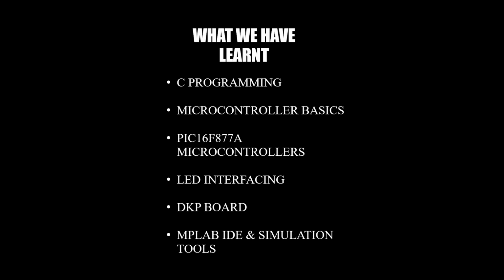As a team, we used these tools for our project: PICSIMLAB for simulation, MPLAB IDE for code development, and the XC8 compiler for compiling our C programs. We divided our tasks so that one member focused on writing and debugging code, while the other member handled simulation and testing to ensure hardware behavior matches our logic.